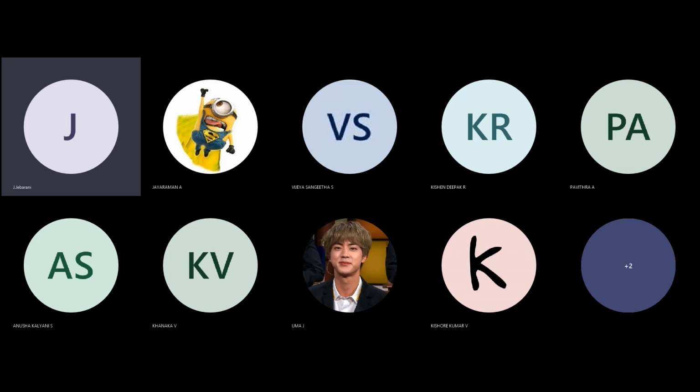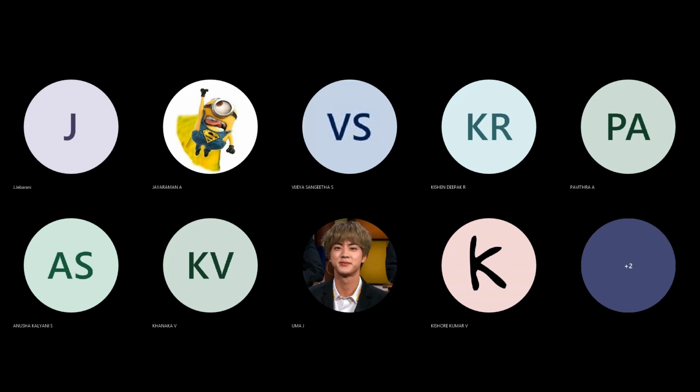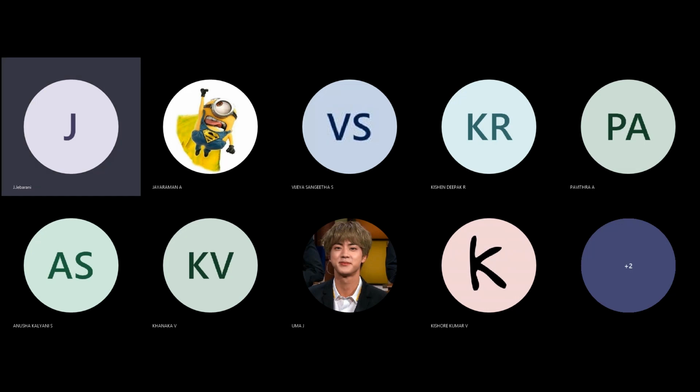The first approach is the short shot approach. In the short shot approach, the polymeric material is partially filled in the mold section, and secondly, the water is injected. In this first approach, the locating pin, that is the water injecting pin, is located near the entry of the mold section.